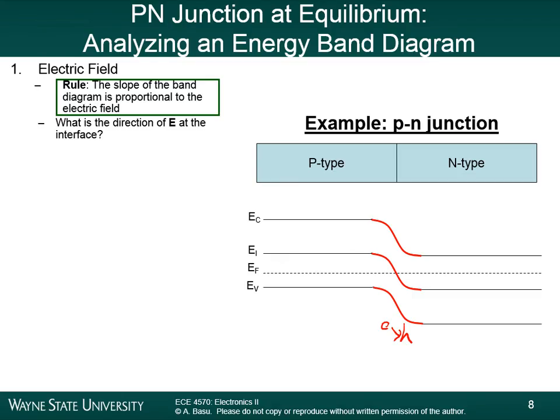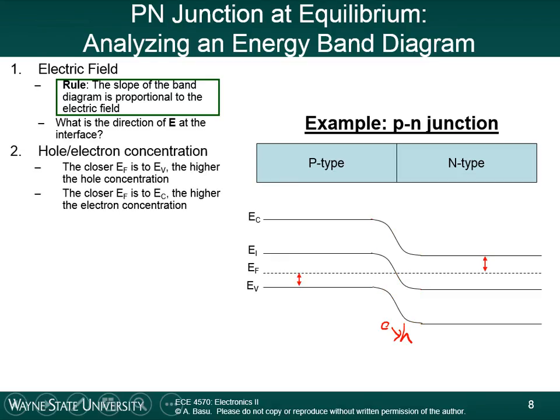I'm getting ahead of myself on the slides here. We'll get to this in a second. So holes will actually end up moving up the slope as a result of this continued event of electrons occupying the hole. The hole will move up to higher and higher energy states. Electrons move to lower energy states, holes move to higher energy states, because electrons always like to occupy the lowest energy state. So a hole moving up the slope is referred to as drift current for holes.